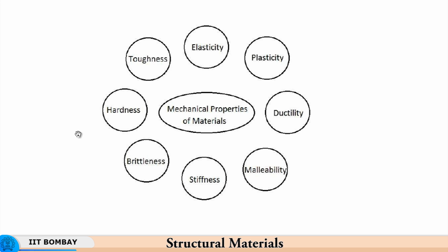Malleability is an aspect of ductility where the material is malleable, meaning it can be flattened, it can be rolled to very thin foils. In electric batteries, for example, you need very thin foils for making electrodes. So you need a very high level of malleability in the material, and so copper and aluminum, from which you can make thin foils of a few microns, say 20 microns, 40 micron thick foils, and so you have a property called malleability, which is an important part here.